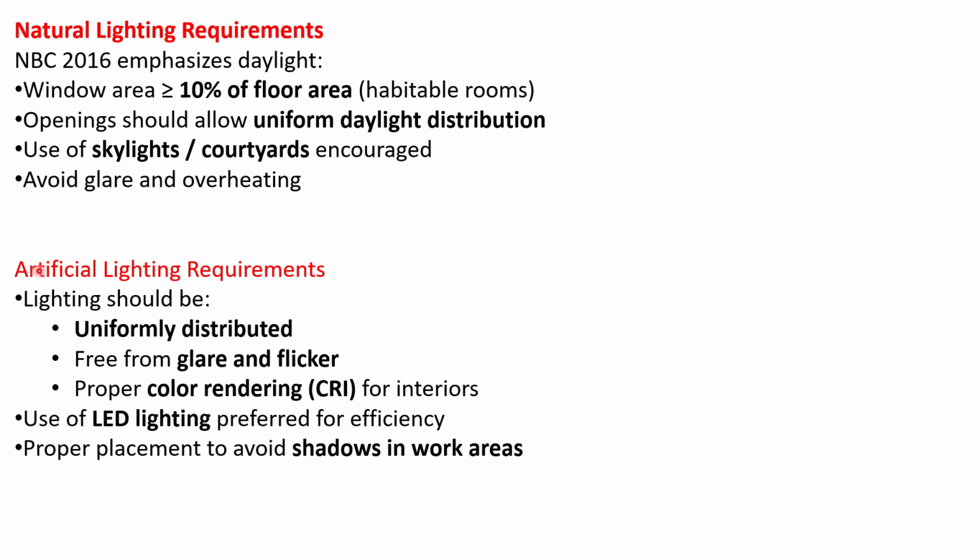The requirement of artificial lighting is uniformly distributed, free from glare and flicker, proper color rendering index CRI for interiors, it should be over 80.